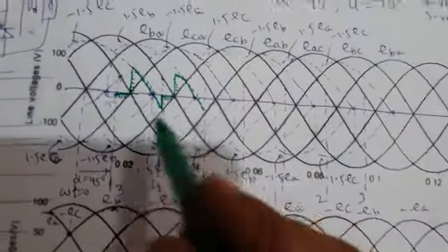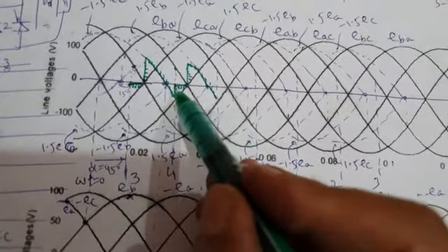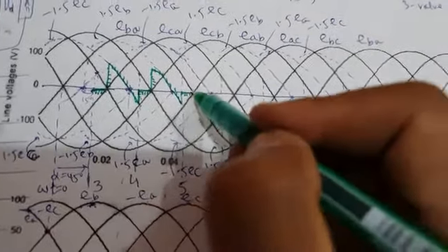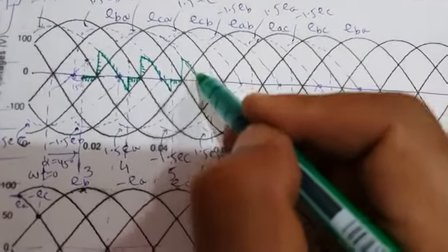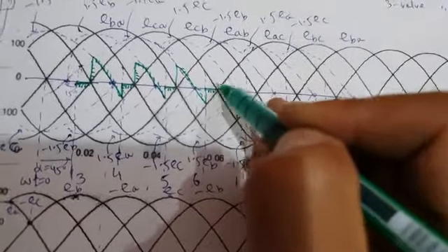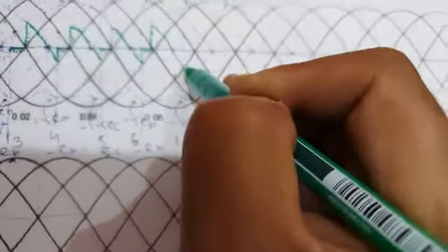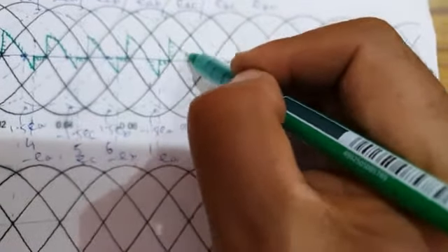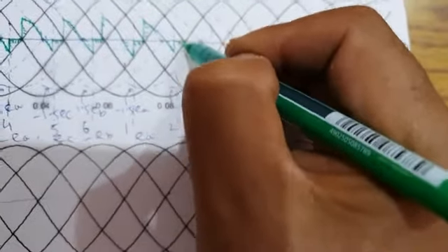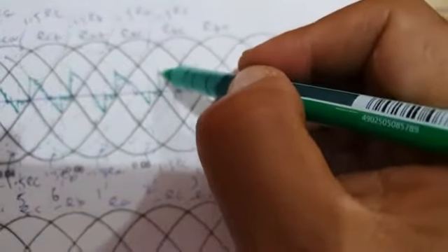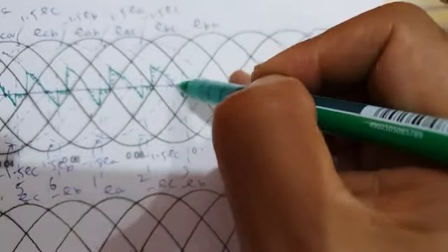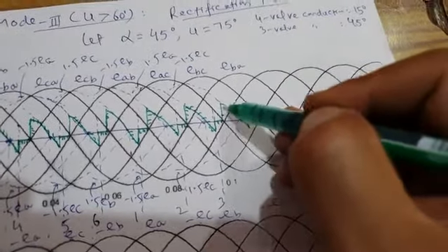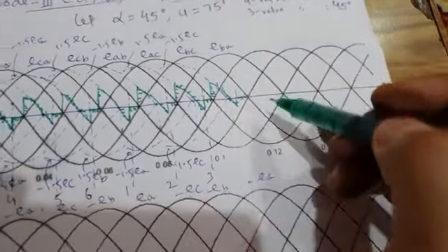And then you don't need to see the table. See, this is your 0 interval followed by this 1.5 times phase voltage interval, then again 0, then 1.5 times phase voltage. You follow this pattern and it will be again 0 followed by 1.5 times phase voltage interval. So you continue like this. You don't need to see the table now. So this completes your load voltage waveform.